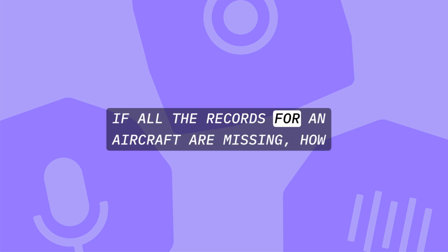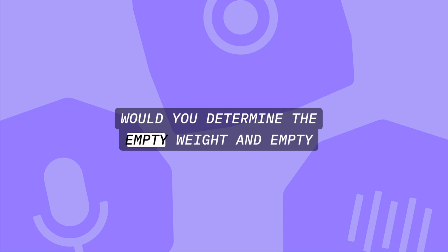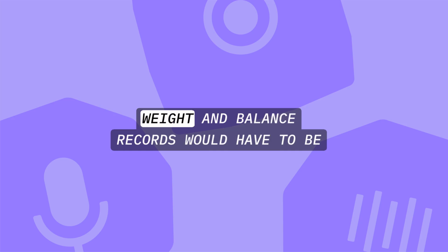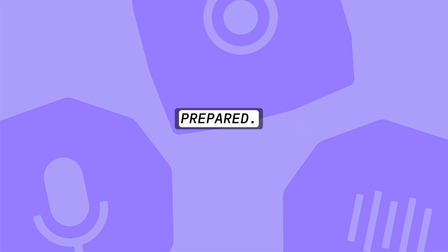If all the records for an aircraft are missing, how would you determine the empty weight and empty weight CG? The aircraft would have to be weighed, and new weight and balance records would have to be prepared.